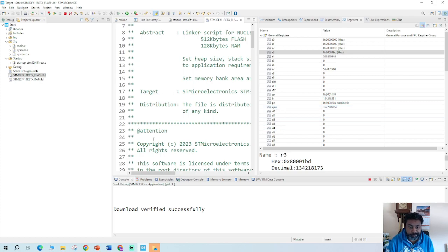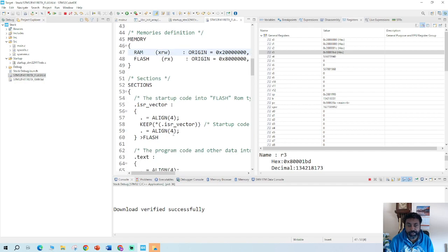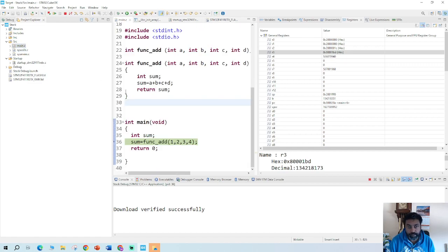So I'm just pointing out where they are and how you get that into the program that I'm going to show you, how you have to include that assembly language to move or load from MSP to PSP, main stack pointer to process stack pointer.